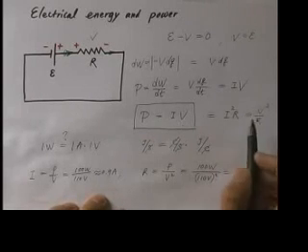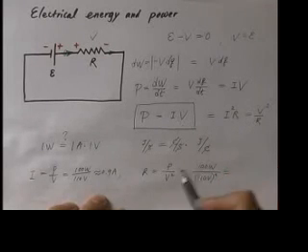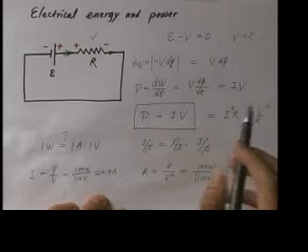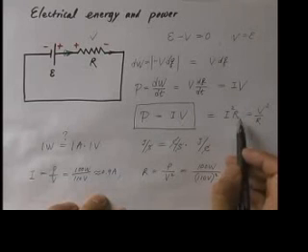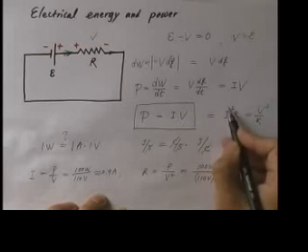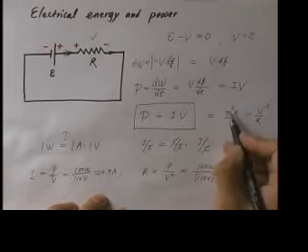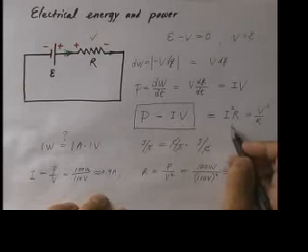And these power transmission lines, even though they're made of copper wires, which are excellent conductors, because of the very long distance, R could still be large. That means you could potentially waste a lot of electrical power just transmitting the power through. To reduce that, we can try to reduce the current. If the current goes down by a factor of 2, then the power lost goes down by a factor of 4, which is a good thing to do.